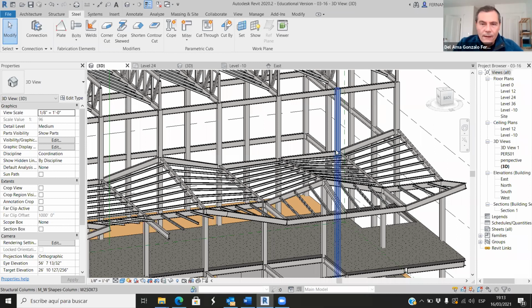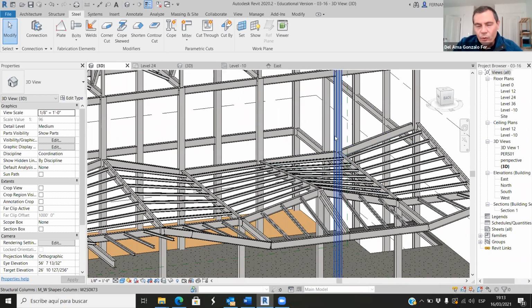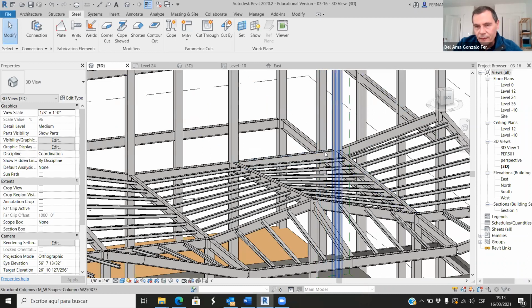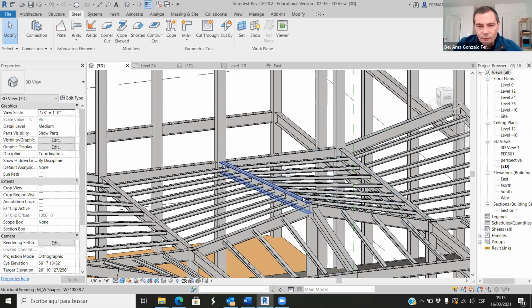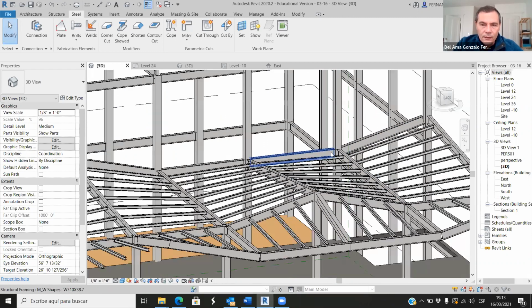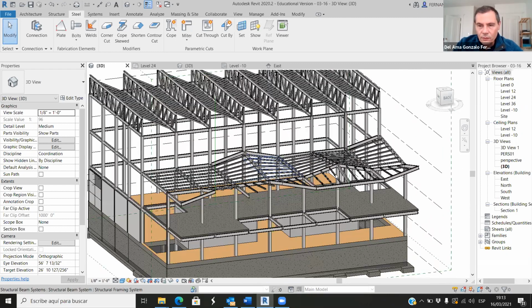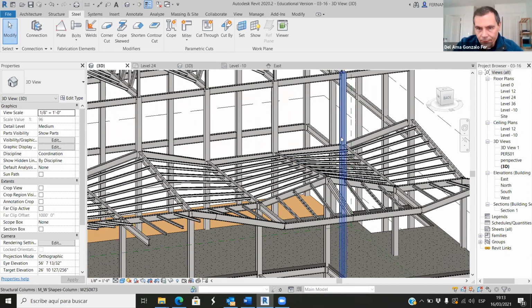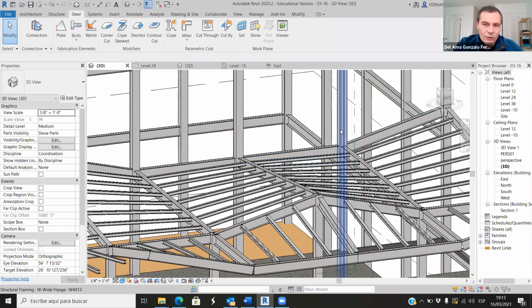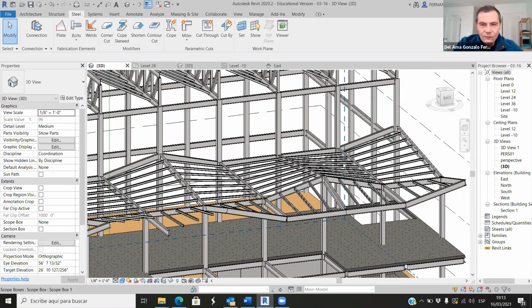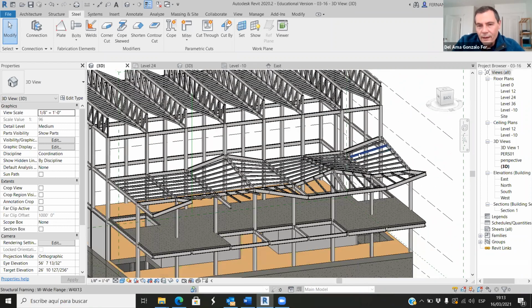Yeah, we can do anything. But I think that will be a weak point when it comes to water leaks or infiltration. Here, there will be a weak point because we are forcing water to go that way. It's more intelligent to force the water to go outwards. So we have to move the water down and out. Here we are moving the water down and in, because we are forcing the water to go towards the building. We can solve this. We can use more waterproof elements here, or we can protect this wall. But this is a design flaw. So why, if I can solve this, why do I need a mistake?